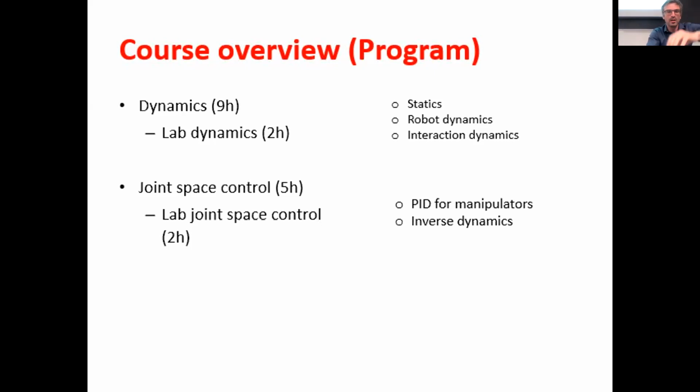And finally, we will introduce the control for a robot, for a manipulator specifically, extending the idea of the PID controller for one single motor to N motors, so to all the joints of the robot that move together to achieve a certain motion of the end effector, for example. And in all this control, whenever there is more than one degree of freedom in the robot, we will have interaction between the different links of the robot.